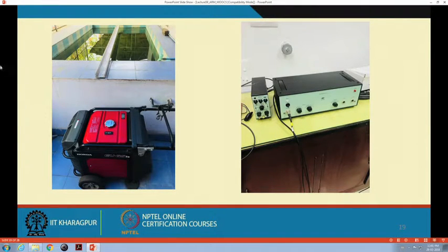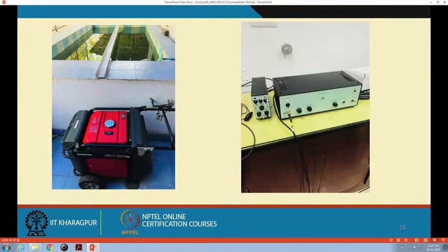We do a lot of work for the Indian Navy. This is an underwater tank where we put in hydrophones and, of course, an acoustic pinger, and this is the amplifier for driving the acoustic pinger or the hydrophones, which are usually charge type equipment. So, a lot of underwater machinery monitoring. We have transducers for underwater vibration and noise measurements, because people would like to know the condition of underwater machinery. So how do you measure their noise and vibration? By hydrophones and underwater accelerometers.